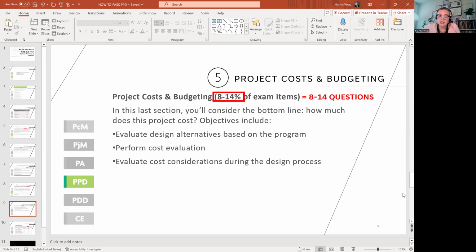But if you specify high impact windows and the owner wants cheaper windows, but the project is in a hurricane prone zone, like Florida, do not do that, because that is going to impact the integrity of the envelope, and that is simply dangerous and not allowed by the local code.